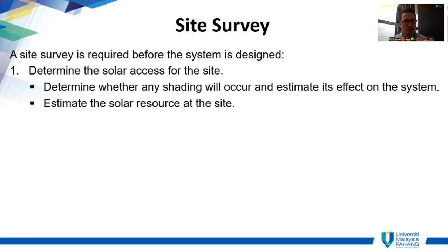So that's why it's very critical for you to go to that place, bring your solar irradiance meter, bring your sunshade tools or a solar pathfinder to verify whether shading throughout the day is covering your PV modules at any side of the PV array at the place where you're going to install. Look at the place, for example, from 7 a.m. to 7 p.m. You must confirm there are no significant shadows that can affect your PV system.